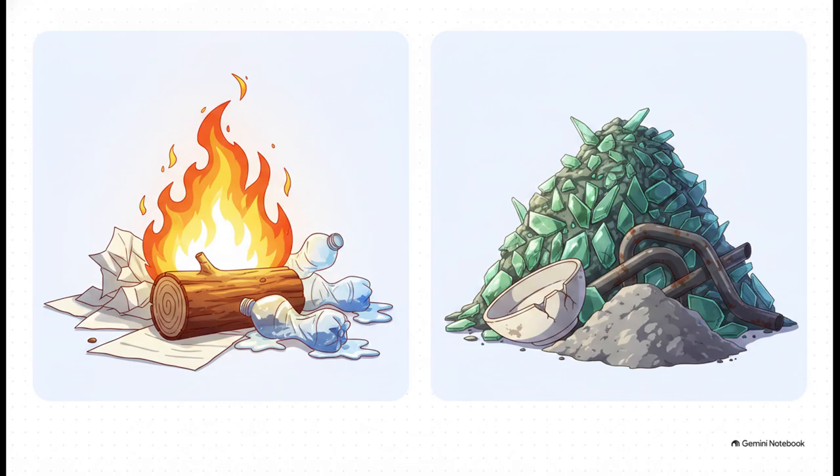On the flip side, we've got the non-combustibles: glass, ceramics, metals, dust, and ashes. These inert materials generate basically zero heat, yet they make up 12 to 25% of dry solids, so they're literally just adding dead mass to our whole system.